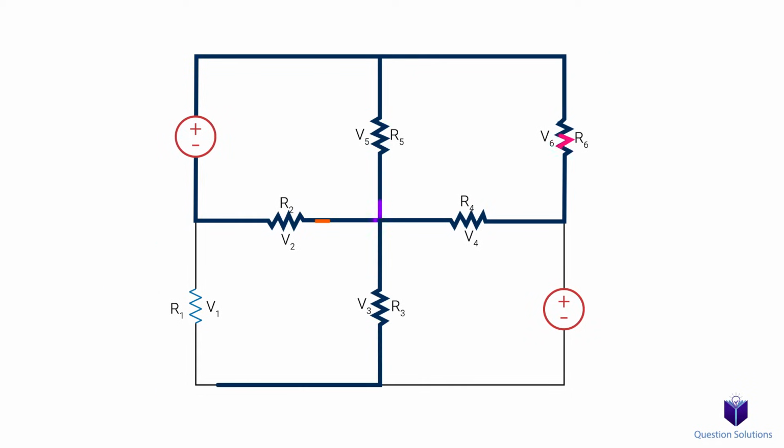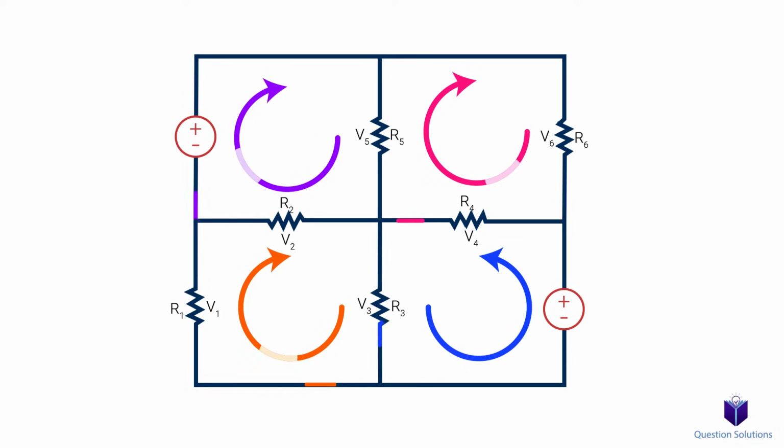You're used to currents being in circuit elements, but a mesh current is an assumed current flowing in our whole mesh. So here we have 4 mesh currents. The directions you pick for them, so clockwise or counterclockwise, is completely up to you. You get the same answer regardless of what you pick. If you end up with a negative value, then you know it's opposite to your assumption, but the magnitude of that value is correct. The next step is to write a KVL equation for each mesh.